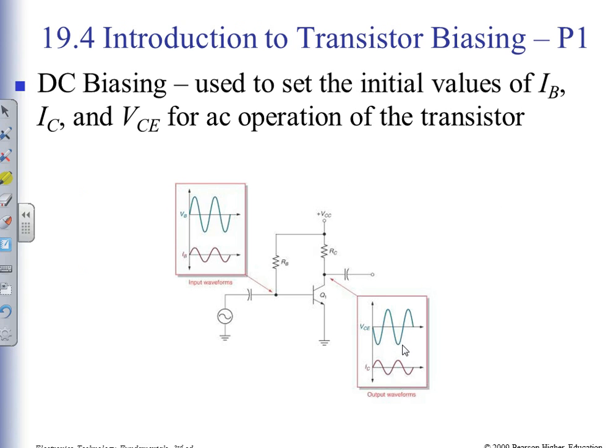All right, back to here. So now I've got some AC signal going into my base. So I've got an AC voltage coming in. I've got a blocking capacitor. This is blocking the DC from getting out of where the transistor is or going out of that area too. So I only have AC coming in, I only have AC going out, and I'm going to have some AC gain associated with that signal, and I'm going to have a little bit of voltage coming in, I'm going to get a lot of voltage coming out.